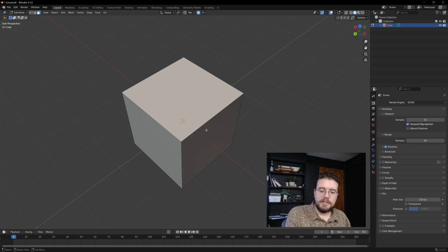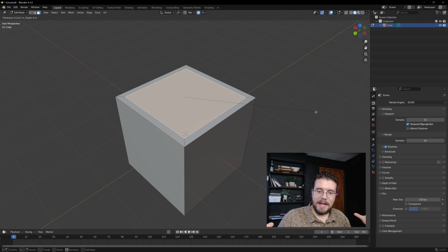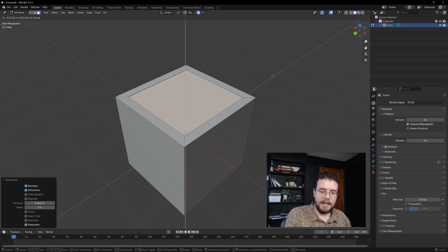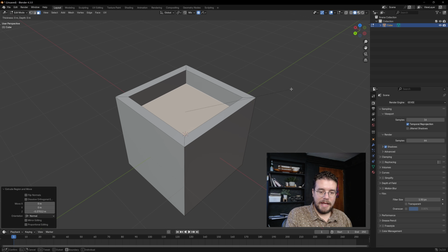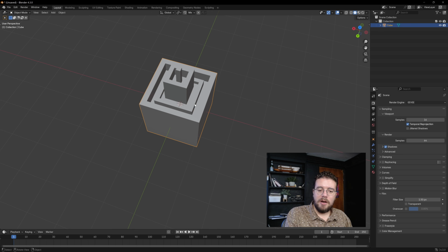And I want to show you what's called the Inset tool. The Inset tool, believe it or not, is just I for Inset. If you press I, you can see it insets. It creates a face within the face, and that can be very useful. If we were then to do something like extrude, we could extrude in on itself, inset, extrude, inset, extrude, inset, extrude. You get the idea, hopefully, of how these tools work. Inset and extrude are 2 tools that work very well together.